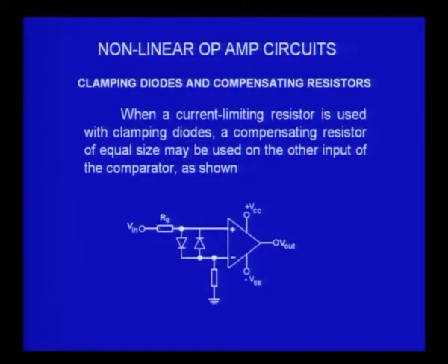There is also another important consideration that you should take into account. Even though an op amp is a wonderful device, almost an ideal device, it is not quite ideal, in the sense it does have a difference in the 2 input bias currents, there is an offset voltage and several other things that come because of the not very ideal situation. So you would find there are 2 input terminals and the voltage is compared between these 2 terminals. The 2 voltages should correspond precisely to what we set with reference to that. If it is not, then it will become more complicated.